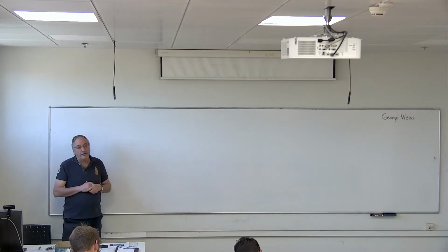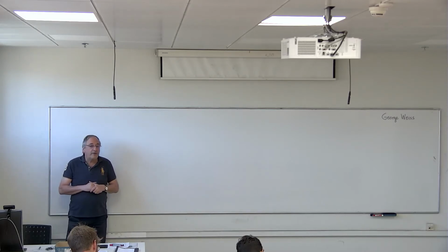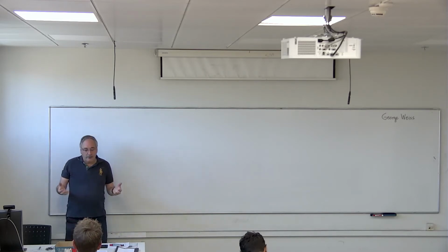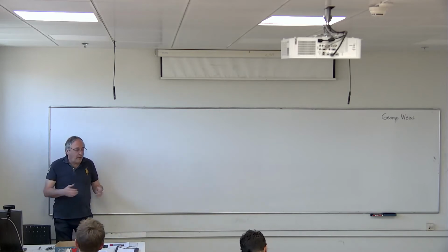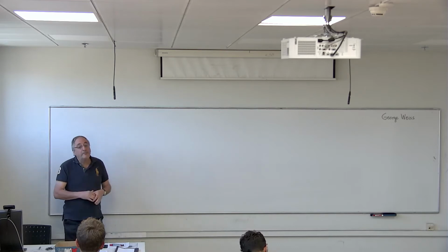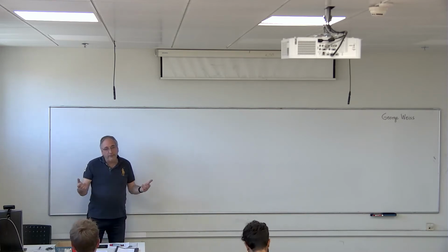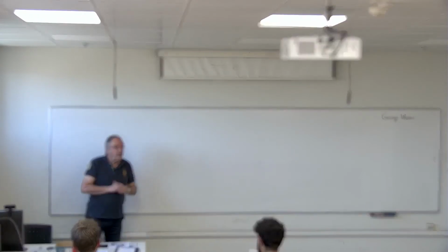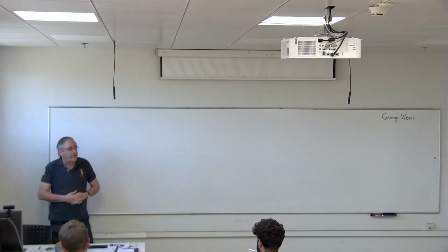some of these little generators produce power at a frequency which is not synchronized with the grid. For example, many local generators, distributed generators, provide sinusoidal voltage at a much higher frequency than 50 Hertz. So that's one problem, that some generators, for physical reasons, rotate much faster than 50 hertz, and so they cannot be synchronized to the grid.